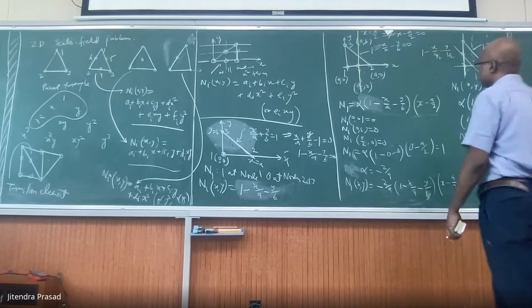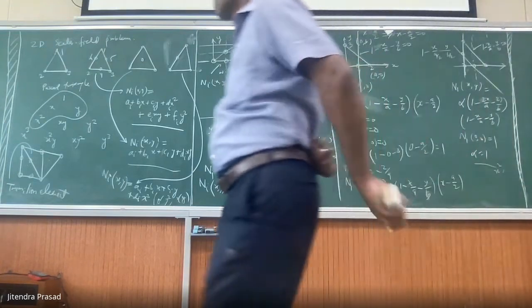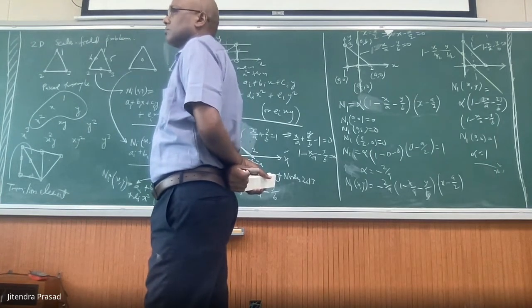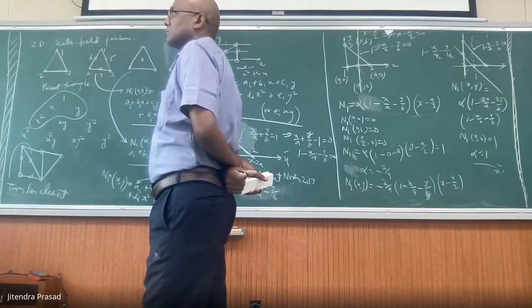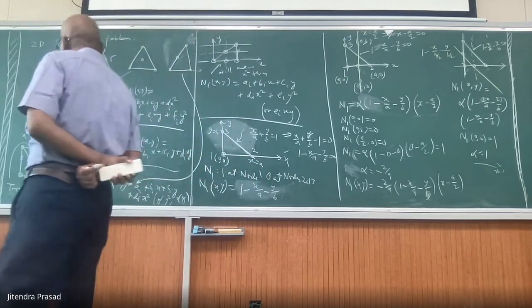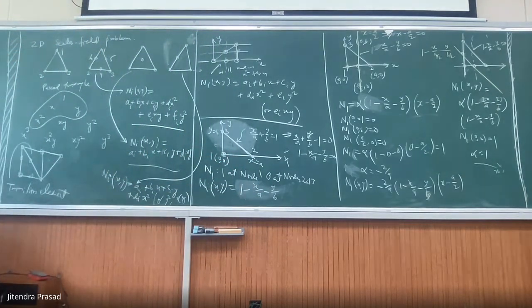So here we are seeing the geometry and deciding whether we should take x square or y square, right? If we don't take that smart step, then the accuracy will change, and the shape function itself is different. So we'll get different solutions, but there is a unique way to have the shape functions. So whatever way you do, finally we end up with the same thing. It is not possible that you have three ways of doing the same thing. Either x square will work or it will not work. If it doesn't work, then you go to xy. If xy works, then you take it. If it doesn't work, you go to y square and so on. It's like that.